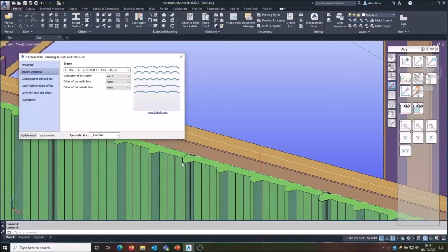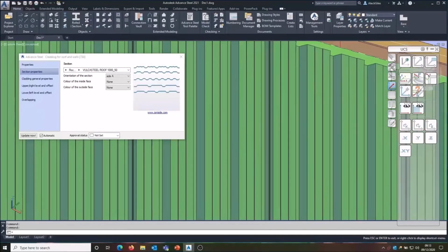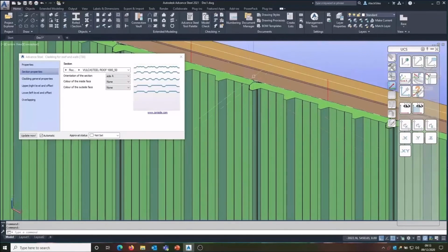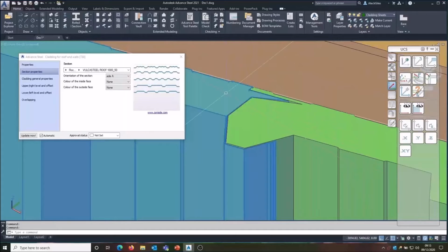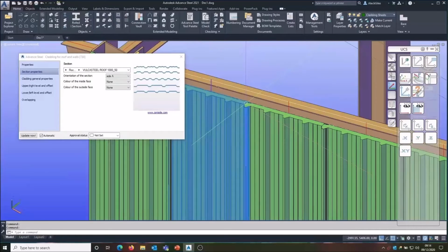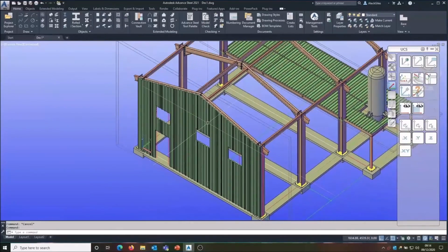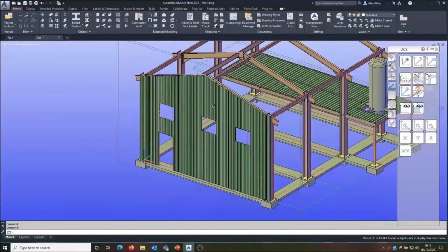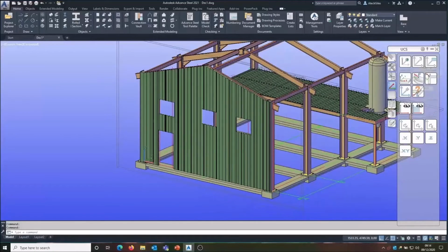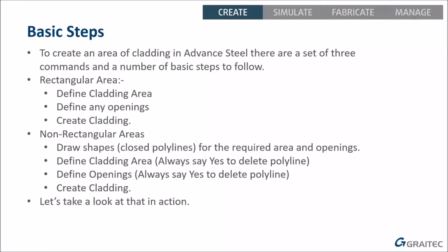So thick insulated panels, that's probably not really all solid steel, is it? That's going to be thin layers of steel with insulation in the middle, but it's just modelled as one thick panel. But look at the complicated shape of the overlap there. So the interlock is modelled on the side edges of the profile shapes, and the macro does the clever bit of laying these out next to each other so the interlocks fit nicely together. So that's one of the main functions of this macro.